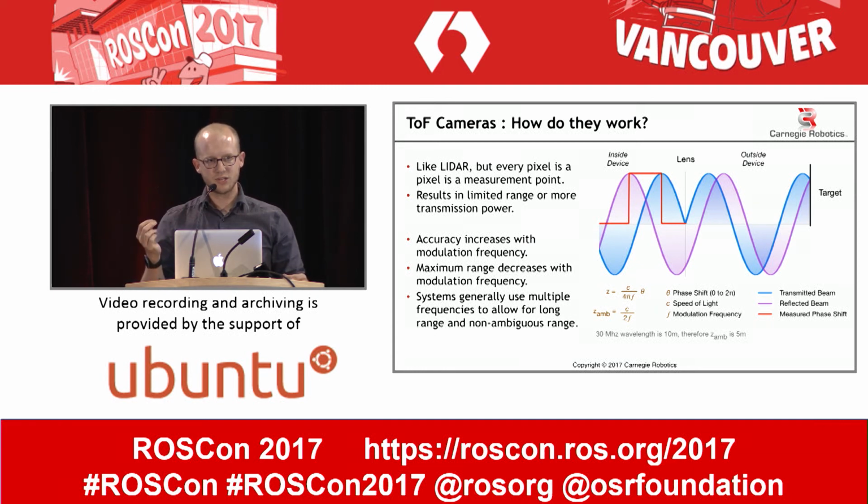This means that you get much better density, but because you're using a much smaller detector that's much lower power, and because you're emitting a broader field of view into the environment instead of a single point laser, the signal-to-noise extraction that a time-of-flight camera has to do is much trickier than a 3D laser. And this limits the range of these sensors as well as their accuracies.